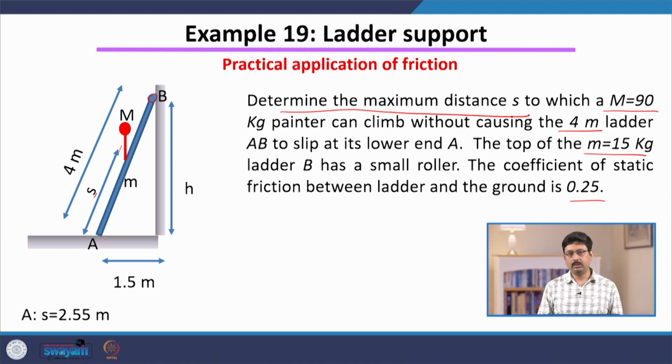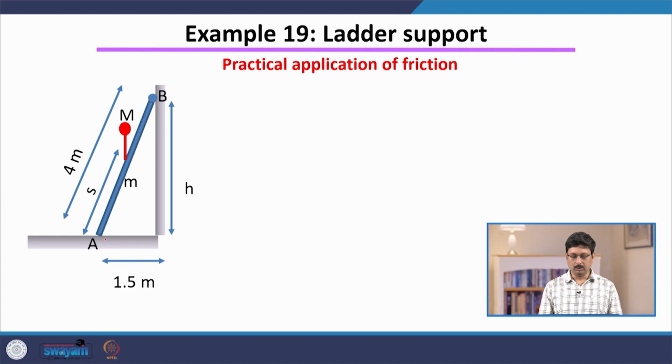Those of you who have climbed a ladder, this is a familiar scenario, and we want to compute this distance s. Again we are going to use the force balance and torque balance approach, and quickly go through the steps and the equations.